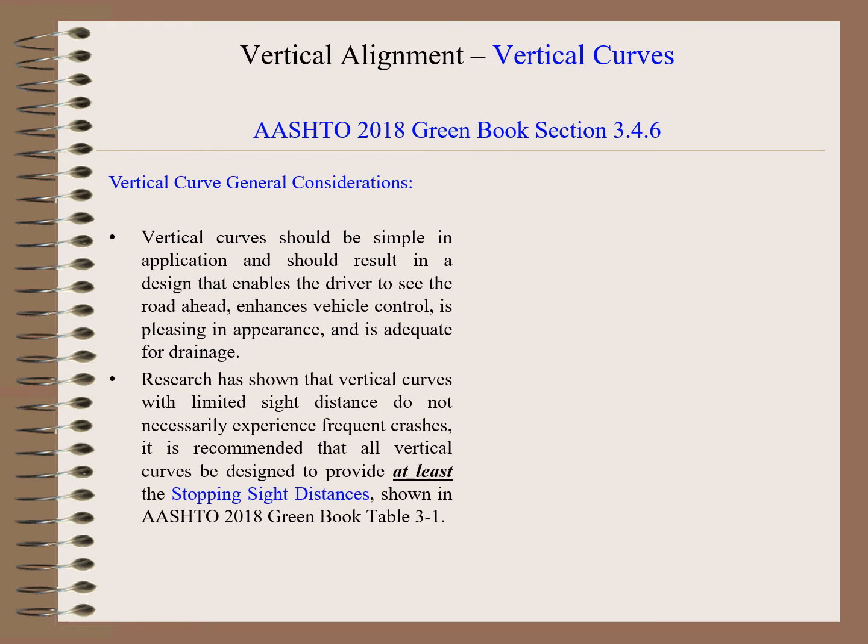Research has shown that vertical curves with limited sight distance do not necessarily experience frequent crashes. It is recommended that all vertical curves be designed to provide at least stopping sight distance shown in AASHTO 2018 Green Book Table 3-1.